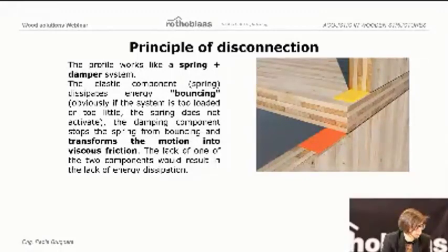If you think about the spring, you need to consider that it is very important to have the proper load applied on the spring, because just imagine that you apply a very high load on a very weak spring. This spring will be compressed and it will not work. On the other side, if you don't apply enough load on the spring, and the spring is very strong, the spring will not activate, and it will remain rigid.